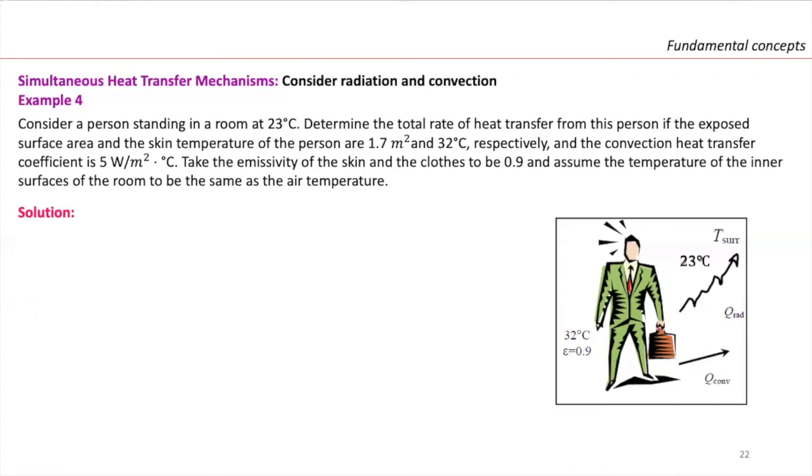So we need to first get what? Convection, and then get radiation, and then add those two watts or heat transfer rates. Because the problem says consider both of them are important. So you have handy your Newton's cooling law, right? We used it in previous examples. We used in the previous example Stefan Boltzmann. So we just need to apply those two.